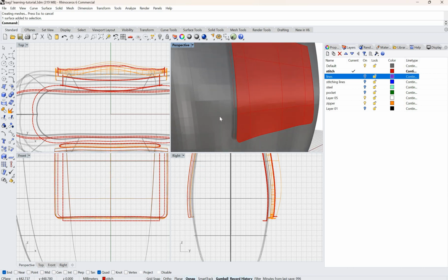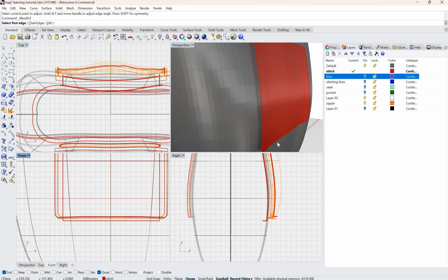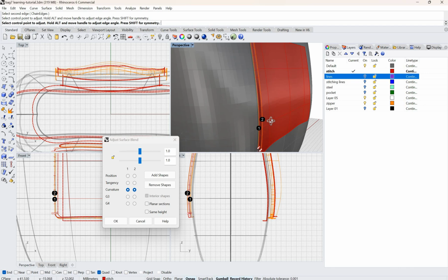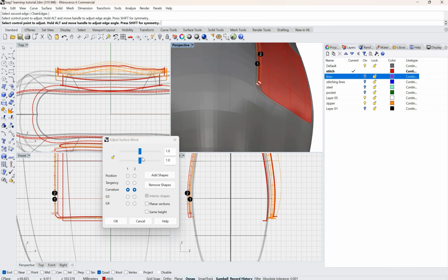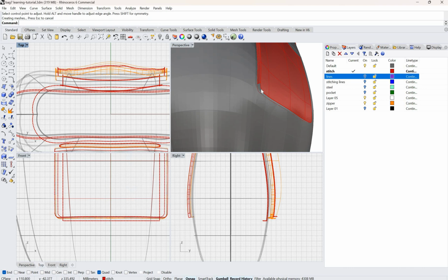First I want to surface blend this. So I will go over here and I'll surface blend. So I'll select this surface edge, select this. So we get an edge like this one, and I can lock this and just remember the number because this is broken. So 0.435, okay, and use the blend surface again.